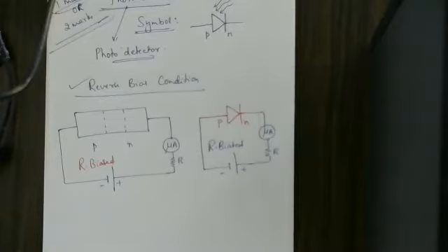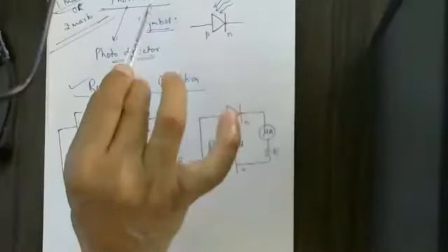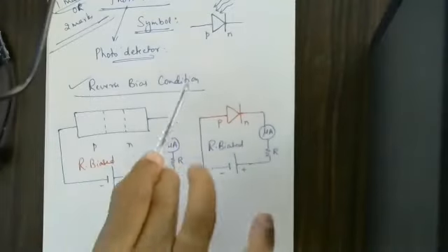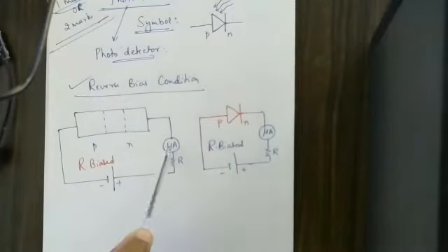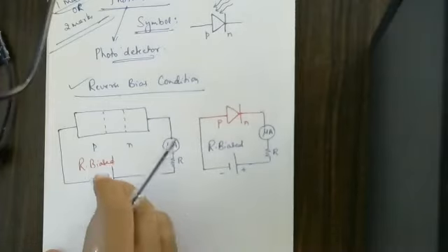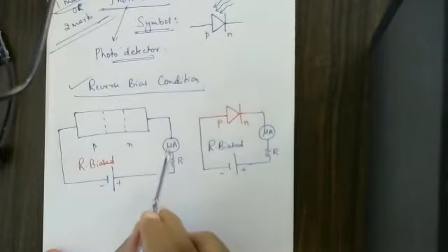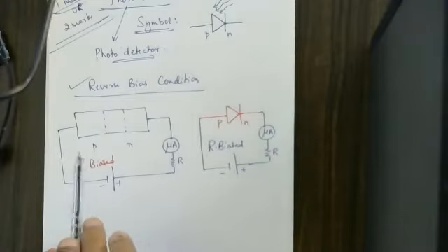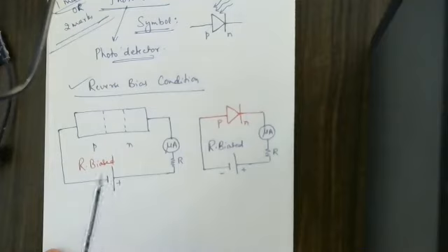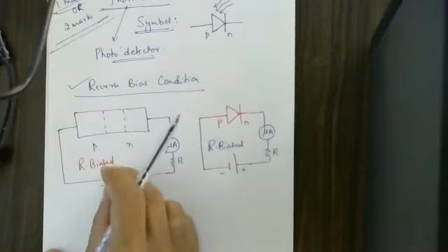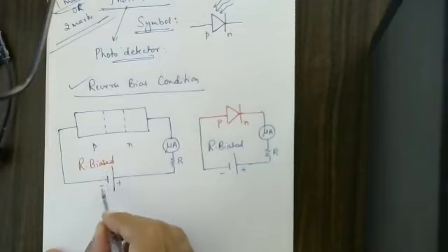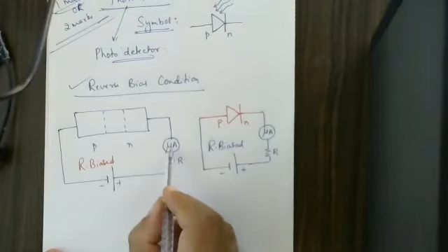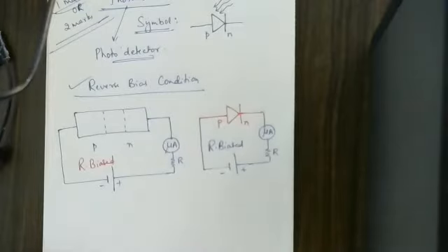Then, how is it working? A photodiode or a photodetector works only under reverse bias. Reverse bias, which I have written with a microammeter, battery, and other things. Here, as the voltage increases, the current remains the same. Take your notes afterwards; you will read about forward bias and reverse bias in semiconductors, both the things, and you will come to know that. As if I am increasing the voltage slowly and steadily, the current remains the same. That current is called the reverse saturation current.